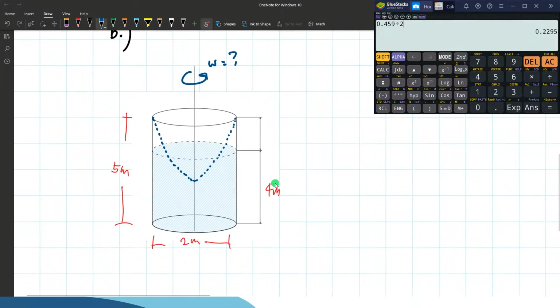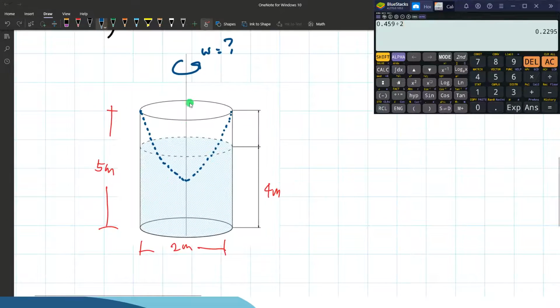In order for us to determine this W, we have to determine the y. That should be equal to twice the distance d. For the second case from the slides, the y over 2, or the half of this depth of the vortex or of the paraboloid, should be equal to d.